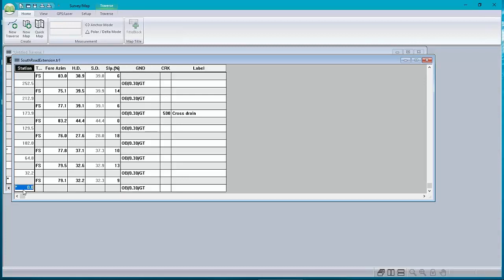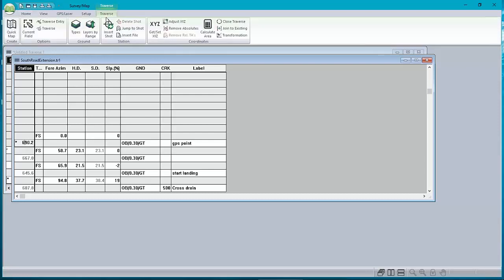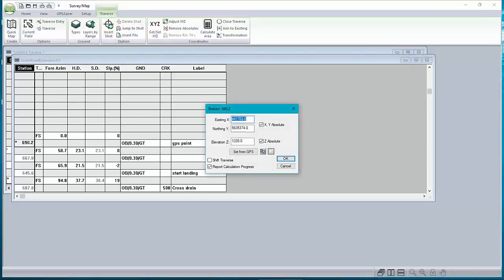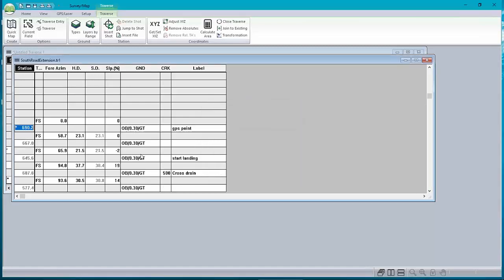And so with a few absolute coordinates, in this case I think there's only 2, with a few absolute coordinates that have been georeferenced, the survey will lie correctly on top of my LiDAR data, and I can make a road design using a combination of LiDAR for side shots and P-line for ground types, comments, culverts, and all the other stuff you're used to putting in P-lines.